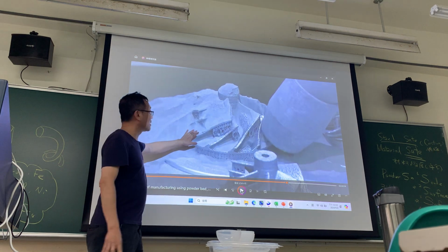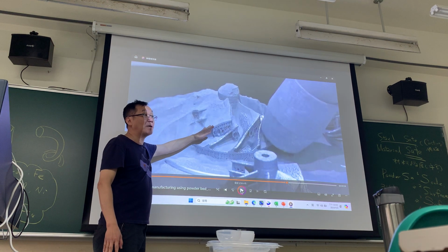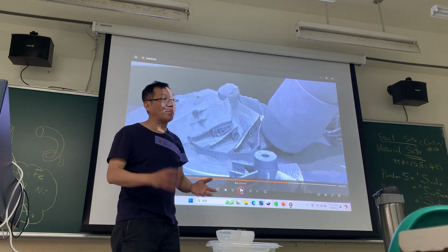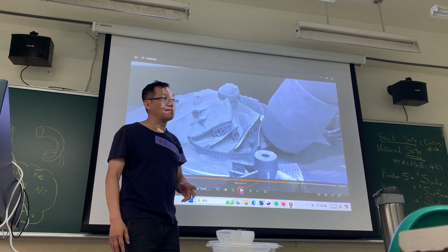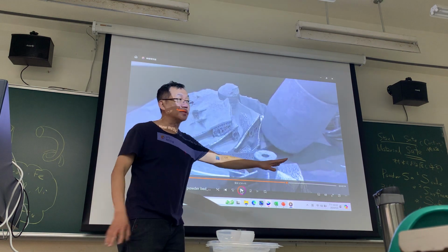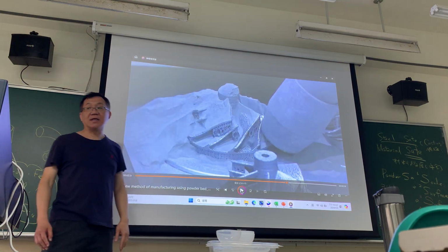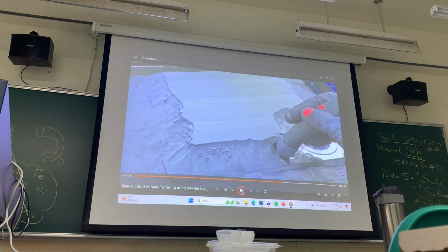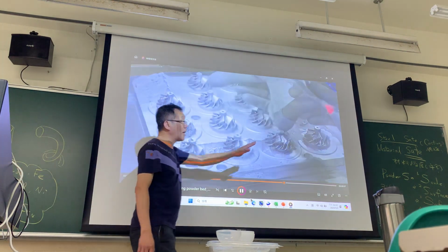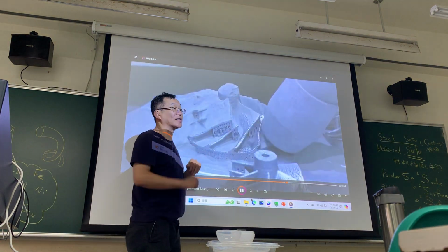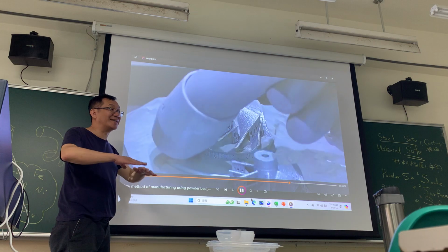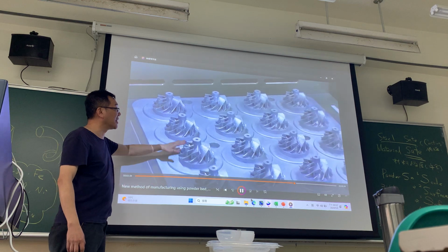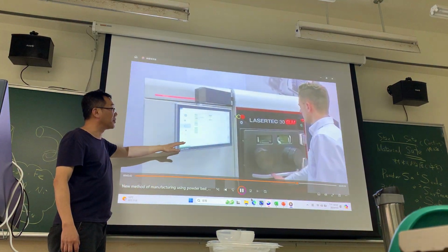Okay, so we just watch that every 3D printing part should have good support for keeping its geometry and to let the thermal separate translation. Very important. Don't forget about it. And you just think about why. Just one layer cannot make more layers because of the thermal. If the thermal is higher and steady, the materials will deform. So in SLM, in powder metal fusion, just only one layer.